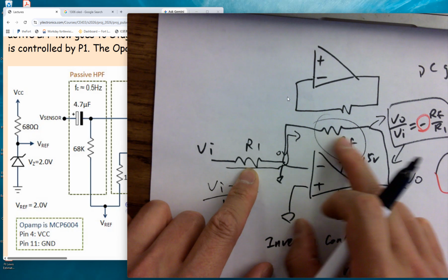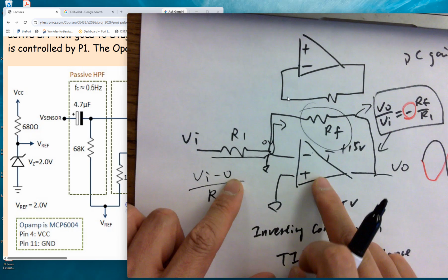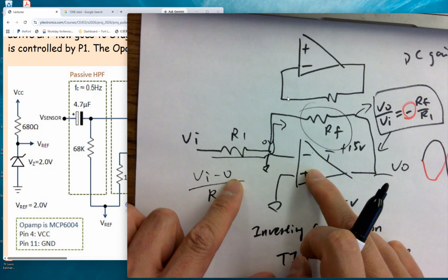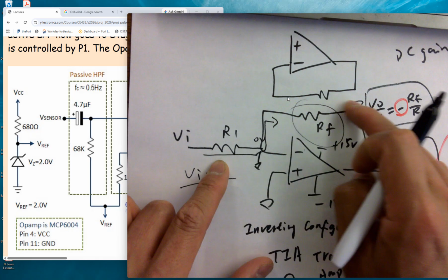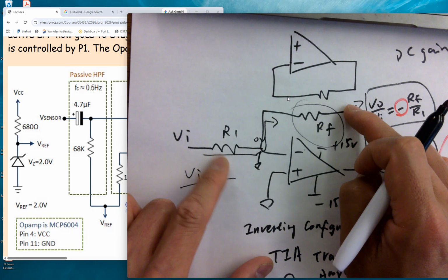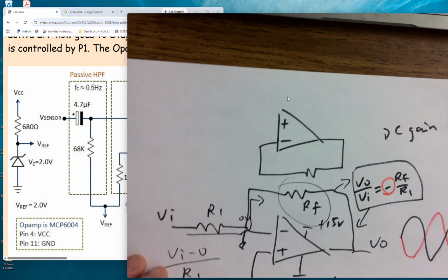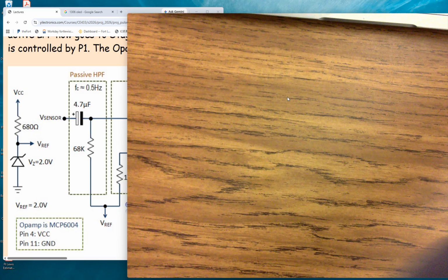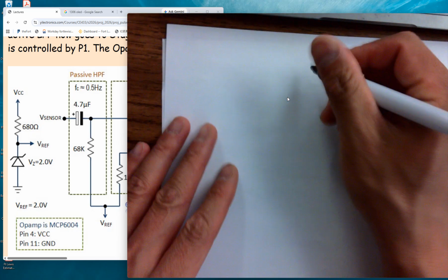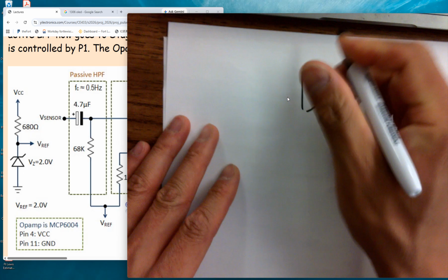So there's no cutoff frequency. It's always going through. This guy probably has a limited frequency in there, but usually it's something else. But this one, there's no filter in here. It's just resistors, linear components. It's just a voltage gain. We don't say DC gain here. Whenever we have a filter, we call it DC gain, right? There's no filter here. But for the non-inverting,